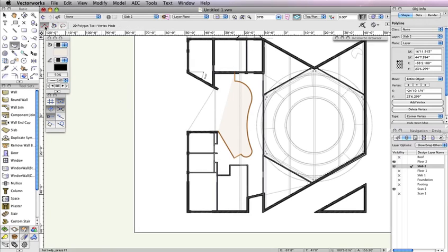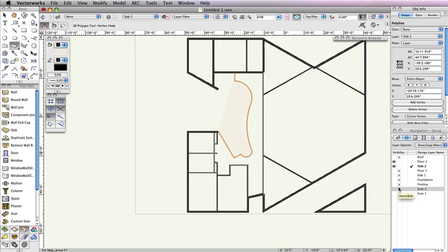The remainder of the vertices should be relatively quick to create, as they are snappable points from the inside face of the walls from the second floor. For that reason, you can set the design layer Scan 2 to invisible in the navigation palette.